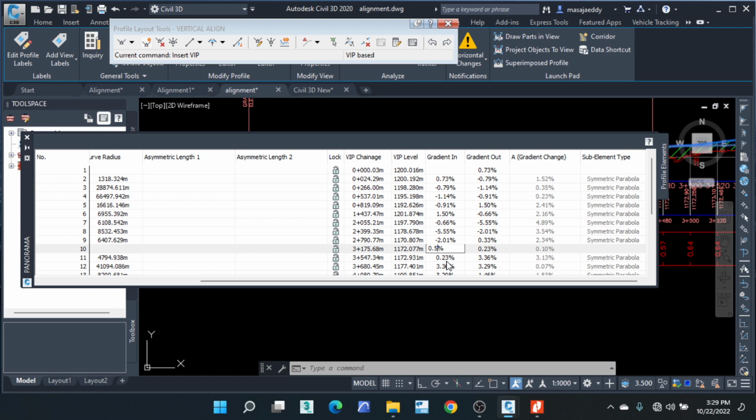For culvert locations, that is for drainage. Yes, it's the minimum slope. How about areas of culvert? There we are trying to increase the fill, because according to the standard, there is a minimum fill. It's supposed to be placed above the culvert, which is 3/4 the size of the culvert.